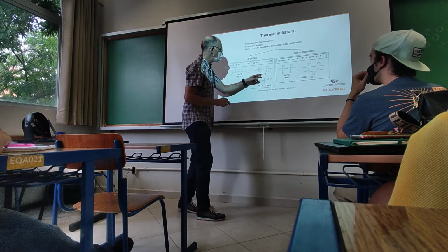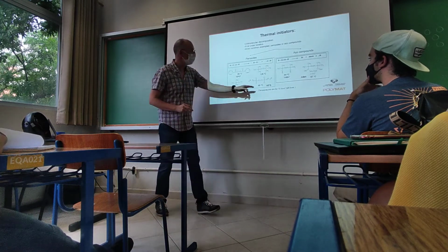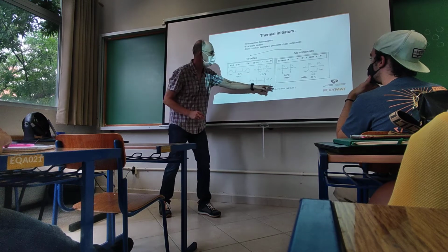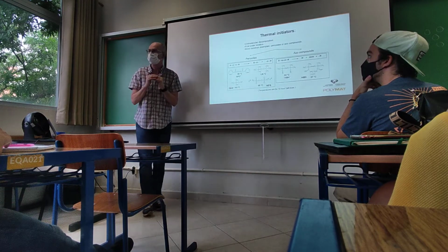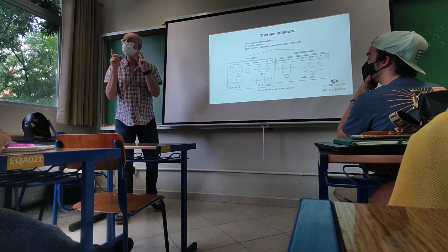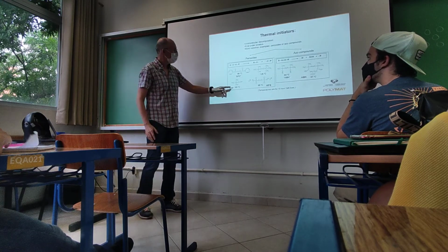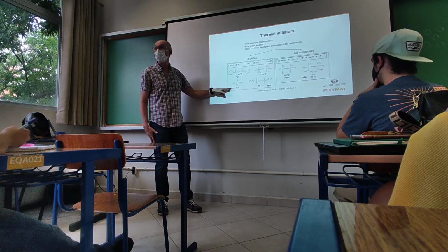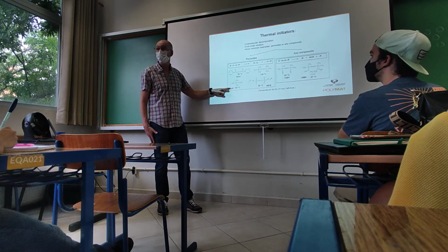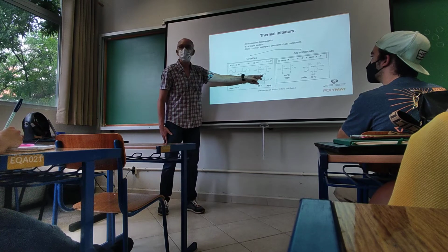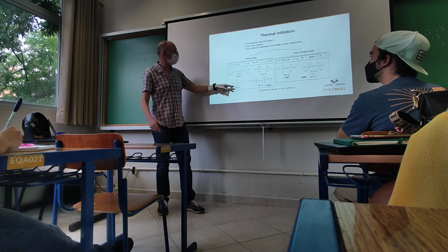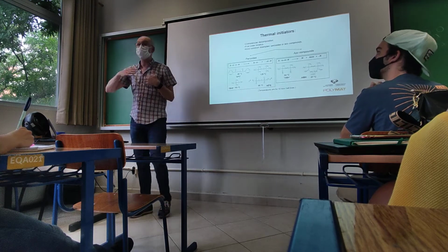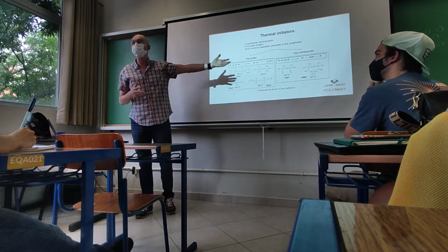The temperatures that you see here are the temperatures at which the concentration of initiator reduces to half in 10 hours. Since we are working with water, these initiators are not appropriate for emulsion polymerization alone, because the concentration of radicals that they will generate will be too low at temperatures below 100, at which we have to work because we have water.